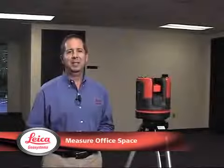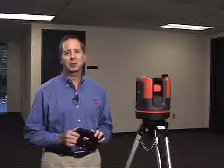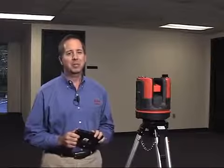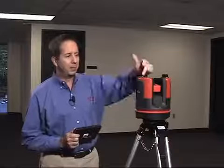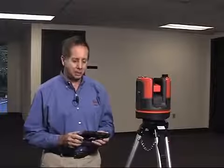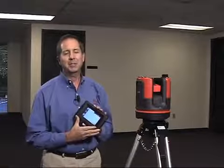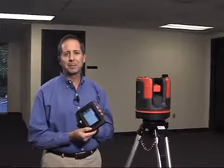Now let's take a look at a typical measuring application inside an office building to locate some doors and some wall planes. In order to do this, we're first going to set up our 3D DISTO, in this case on a tripod. We have powered it up by pressing the red button on top. The unit has self-leveled, and the green indicator light on the top shows me that it's ready to go. Additionally, I've powered on the control unit. It is booted up, and it is also ready to go. We've connected the two via the Wi-Fi signal.